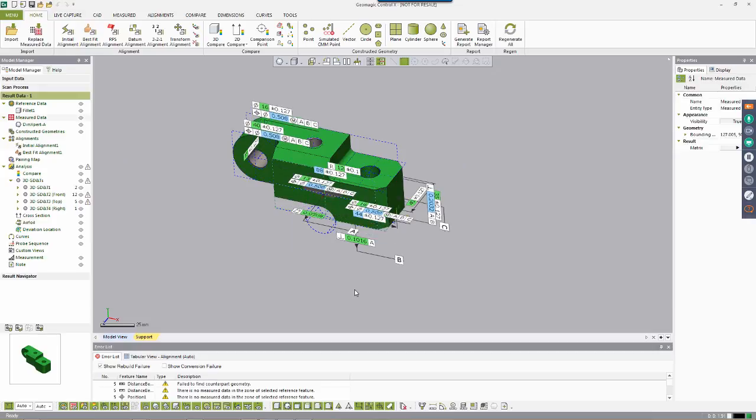If you guys are Control X users, I know we've got at least one in the audience today. One of the neat things is I can save the alignment data with the CAD data, not the measure data, and I can reuse this template over and over again each day. If I've got to measure 20 parts, I would have my 20 measured data and I wouldn't have to do the alignment each time. It remembers that from the initial setup. Makes it very, very cool.